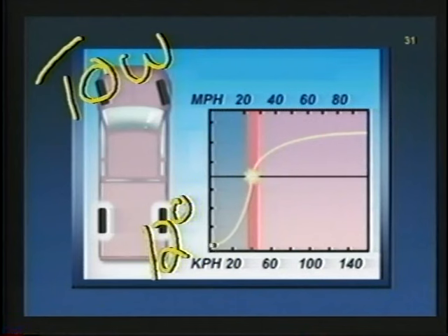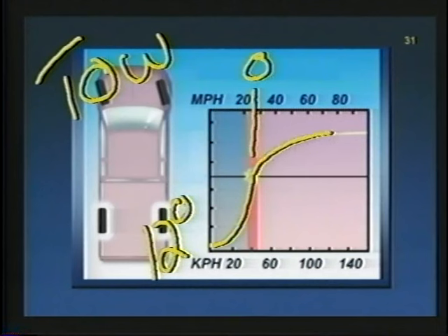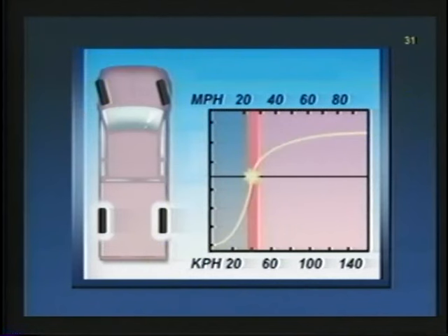But you see very rapidly from that 12 degrees at very low speed, we're going to be dumping that turn radius off. By the time we get to this 25 miles an hour here, we're back to 0. Then we'll cross over into the positive phase. Still have 5 degrees here. So the amount that we're turning the rear wheels really hasn't changed at all, just where we make the transition. That's going to change: 25 miles an hour instead of 45 miles an hour.